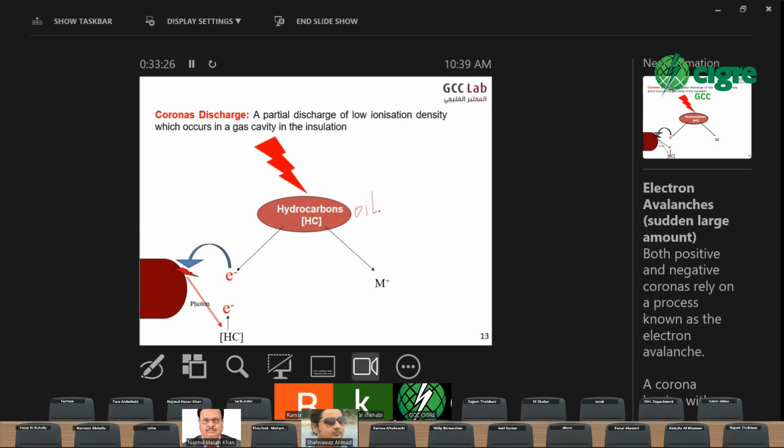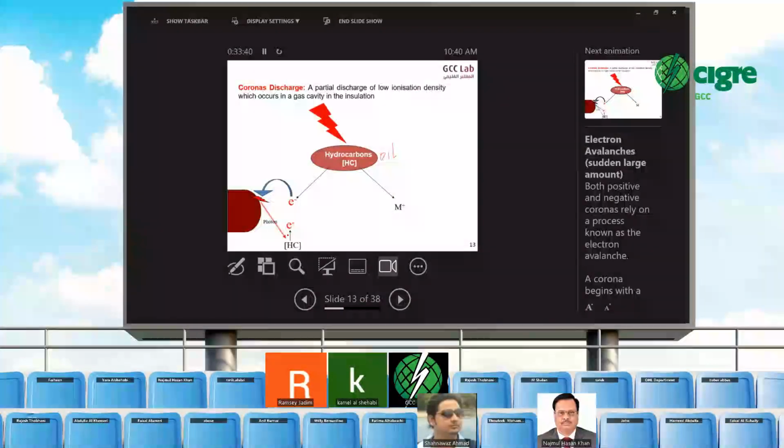Oil. And if you see, if there is a partial discharge affecting the oil, like what we see in the video, some of the hydrocarbons can give me electron, and it's called ionic hydrocarbons. What happens if you have electron inside the transformer?